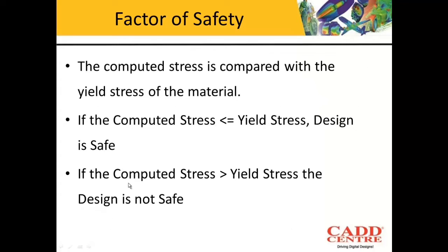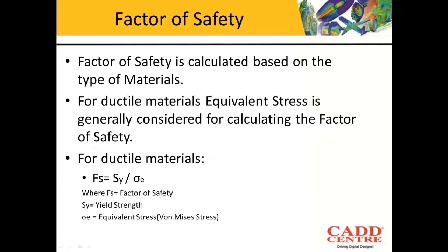If the calculated stress is lesser than the yield strength of the material, your design is safe. If the calculated stress is greater than the yield strength, your design is not safe. Okay. Now, factor of safety is generally calculated for materials. Now, depending on the materials, the calculations will also differ.